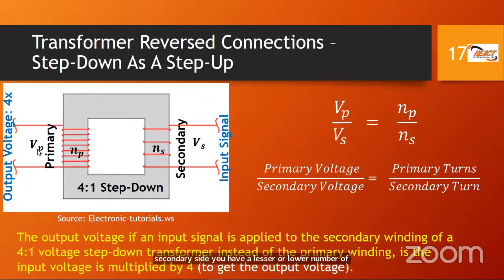Whatever the input on this primary side is, the output on the secondary is going to be less, in a ratio, right? So if it's 200 volts on this side, maybe it's 100 volts on this side, depending on the ratio of the turns. So this is a step-down transformer, but we are saying that this is a 4-to-1 step-down transformer. So essentially, whatever on the left-hand side we put in here, we'll get a quarter out on the right-hand side. That is essentially what it means to be a 4-to-1 step-down transformer.